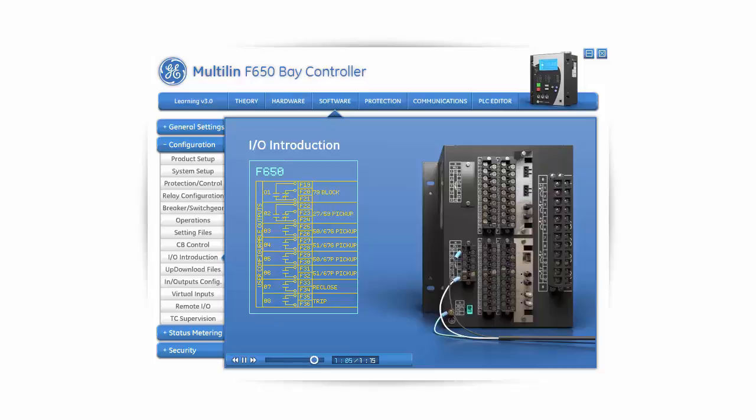The remaining output contacts are configured by default to provide information about the auto-reclose function and the pickup status of some of the important protection elements. All of the contact outputs have the same current rating and characteristics. Each of them, including the trip and close contacts, can be reconfigured if necessary. The procedure is covered in the Relay Configuration section.